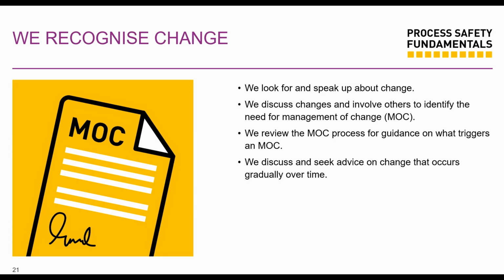And then that new sealant that you're using reacts with some of the chemicals you are processing. Some could react with oxygen, and then you have fire or whatever happens based on that, or you have a loss of containment, you have a leak because stuff has reacted.